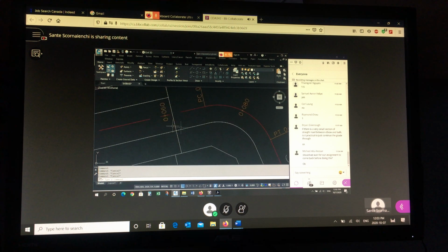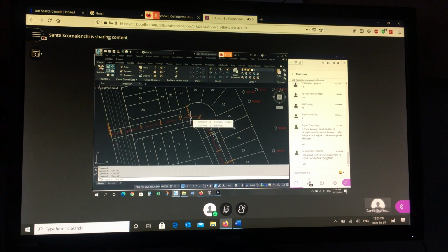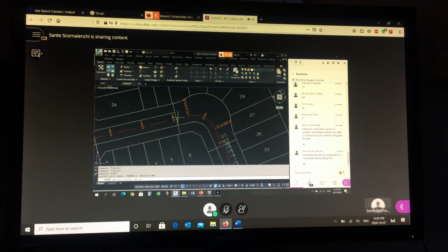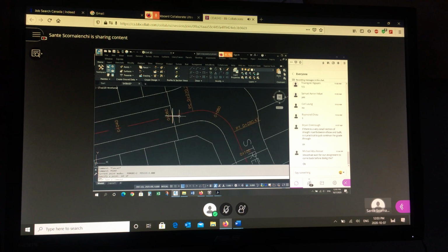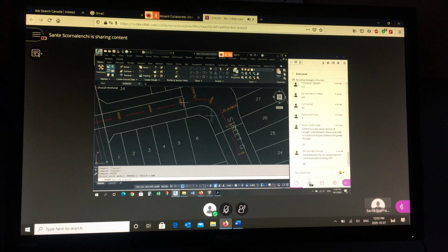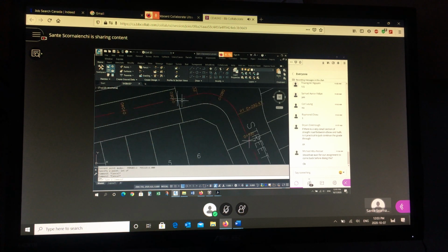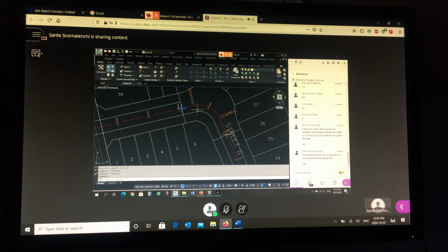So if I want to find that station value, here's a handy tool. I'm going to draw a point, AutoCAD point, P-O-I-N-T, point. This is AutoCAD. And I'm going to snap to that intersection, center line, and that point where the zone starts. So there's an AutoCAD point. Draw another one at the other side. This is the end, intersection. There's another AutoCAD point.